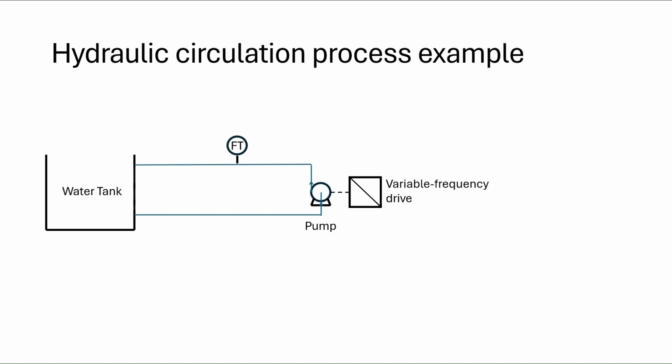And then we feed that into the digital twin, and a digital twin will actually generate a flow from that. So it will calculate the flow based on some equation of choice. In this case, it could be just having a look at the specs of the pump and approximating the output signal through a mathematical function.